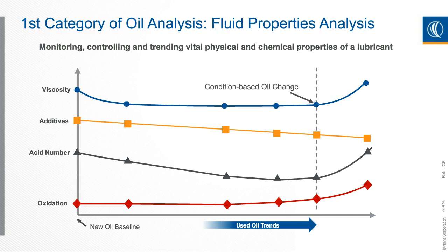You'll see here the viscosity and the acid number. There's an inflection point where they both started changing. They're starting to change at the exact same time, and maybe that means oxidation has started to occur more rapidly, probably because the antioxidants have now become depleted.